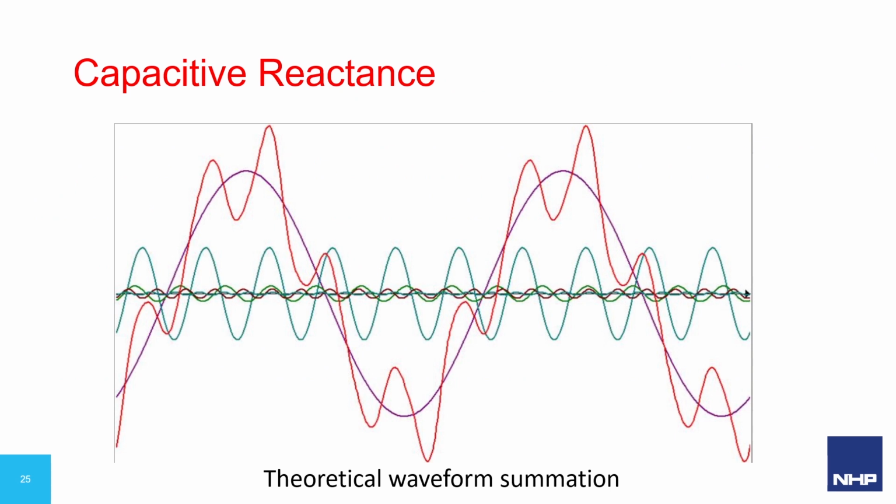So for those of you who do like to do your own investigations and calculations, the formula here: XC, or capacitive reactance in ohms, equals 1 over 2 pi f C, C being the capacitance in farads. In short, capacitive reactance is inversely proportional to frequency. If we remove the imposed increase in frequency, we increase the capacitive reactance and reduce the capacitive leakage along the line.